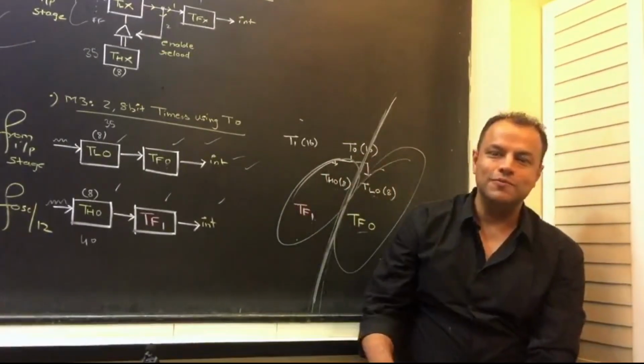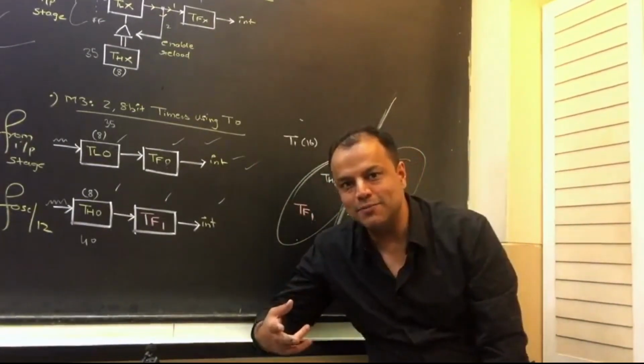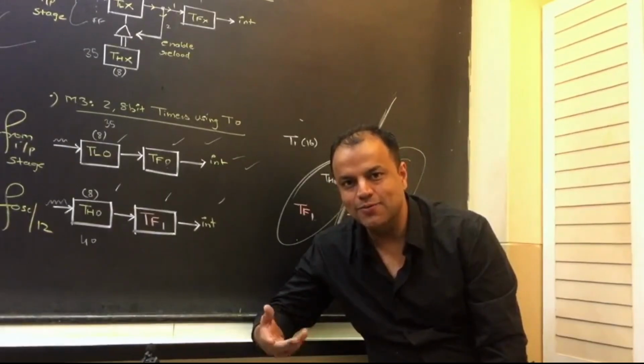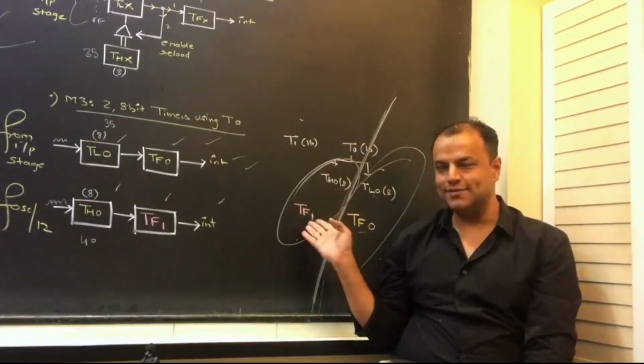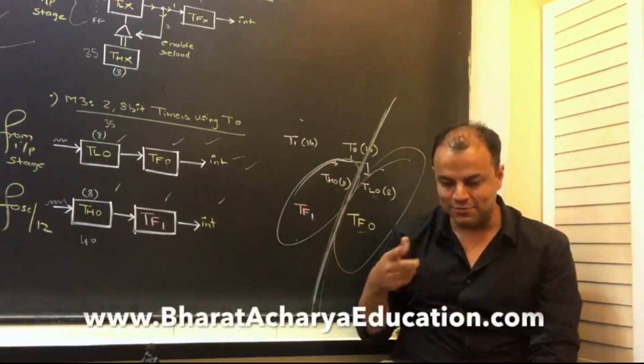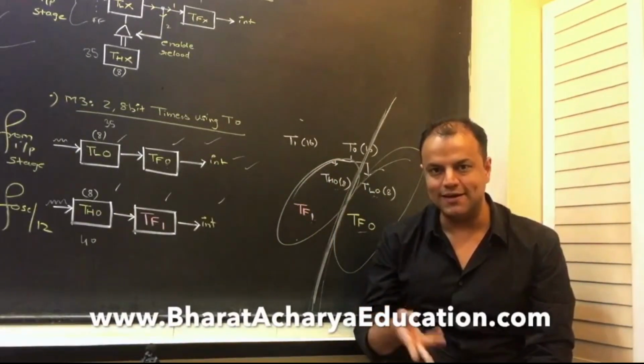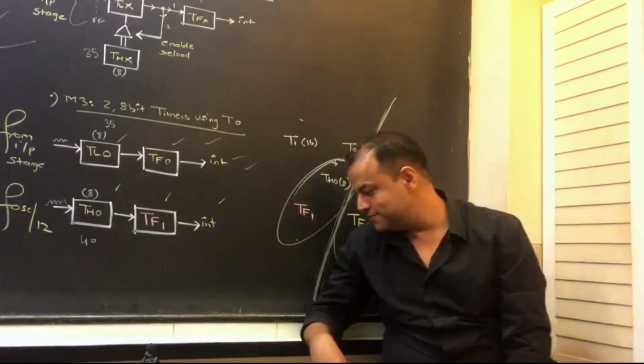Now what is your impression? This is a stupid mode. We had two 16-bit timers. Now in a greed, what have we achieved? We have got two 8-bit timers, that too the ones who work like this. And one stupid 16-bit timer that counts within itself, does not even tell us that it has overflown. So is this a good mode?